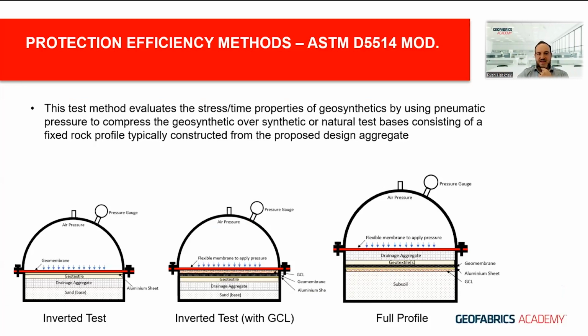As I say, this test method evaluates the stress strain properties of the geosynthetic by using pneumatic pressure to compress the geosynthetic over a synthetic or a natural subbase.